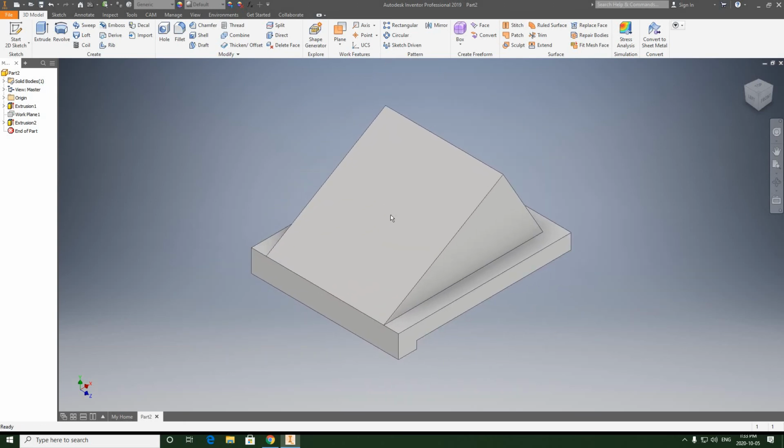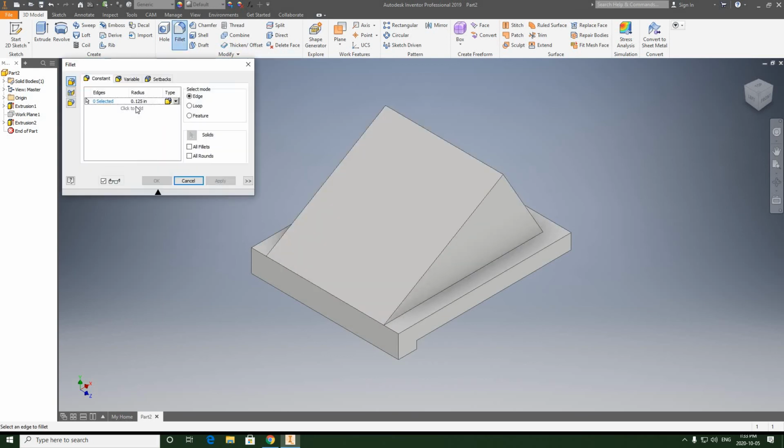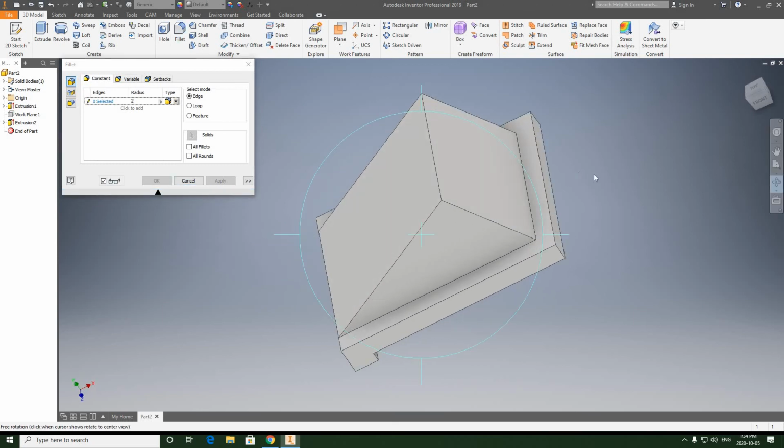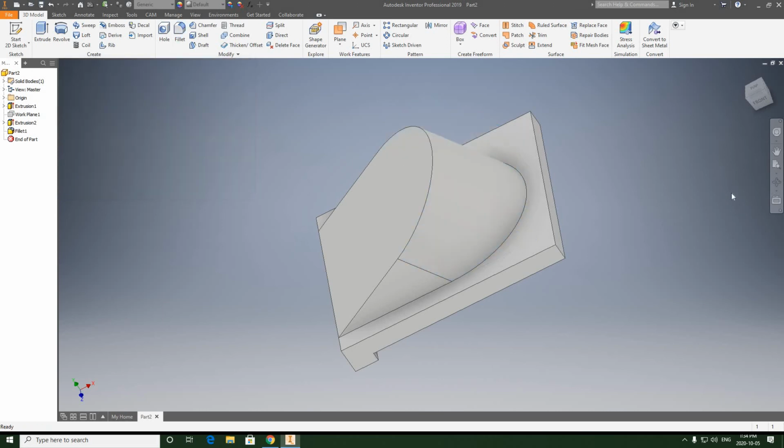So the next step would be to create the inside radius of the washer first. Now, creating the outside one first would cause a modeling error, and I know this from experience. So I'm going to select fillet, and the value is 2 inches. So we're going to type 2. Let's orbit this a bit, and we're going to select this edge and the opposite, and hit OK.